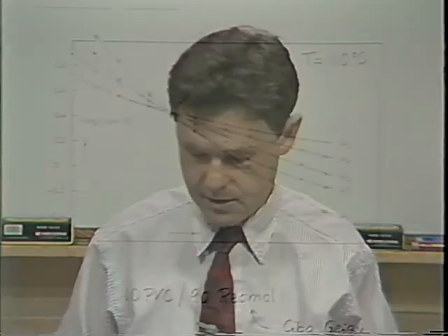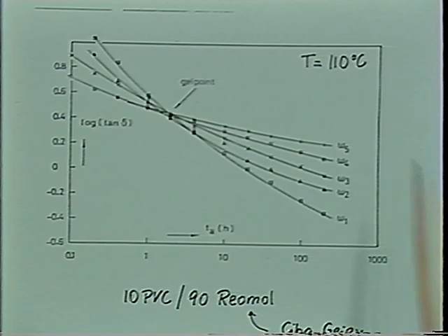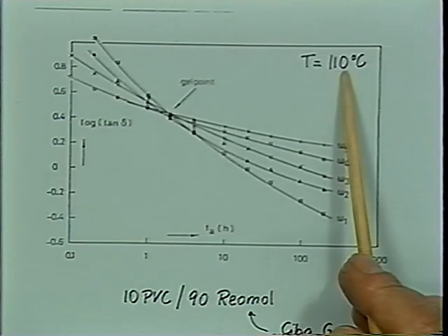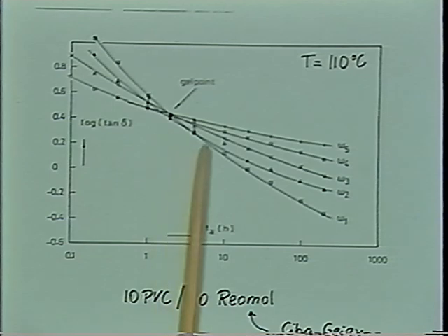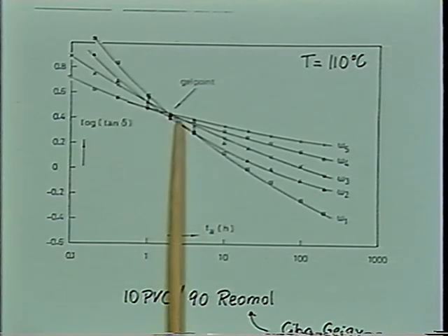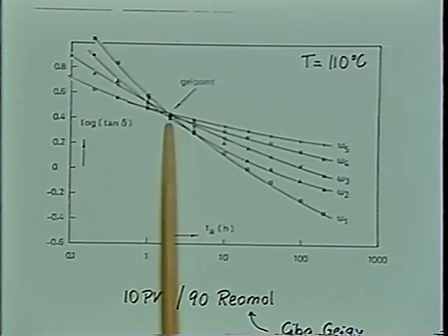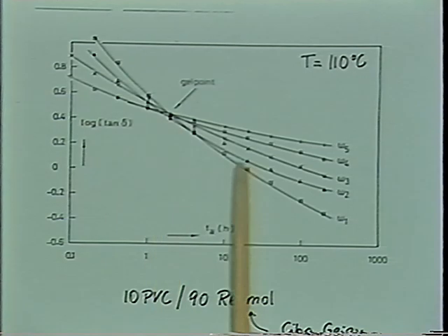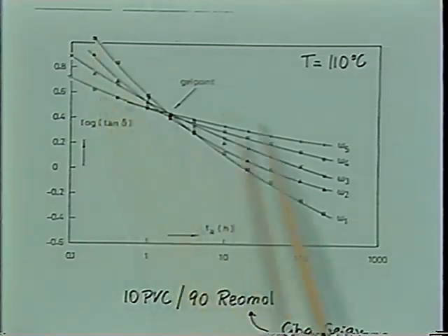The crystallization behavior depends on the plasticizer which had been added. Now he used a commercial plasticizer of Ciba-Geigy and found that at a higher temperature, at 110, the material crystallized nicely. The same polystyrene, also 10% polystyrene, he used here. And it needed a little more than an hour to reach the gel point, but again, it's the same fingerprint.